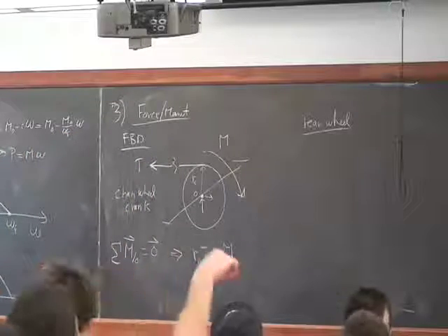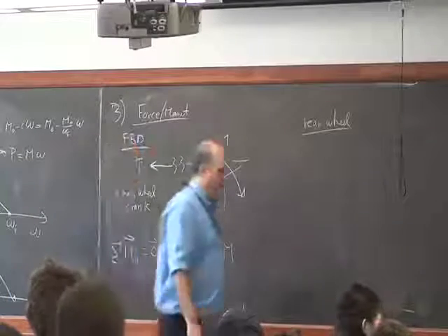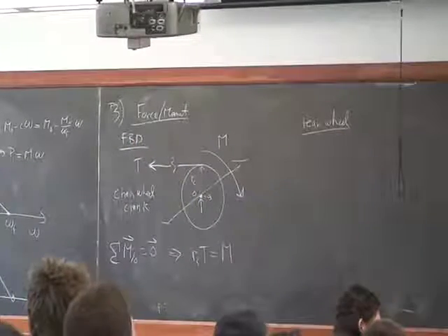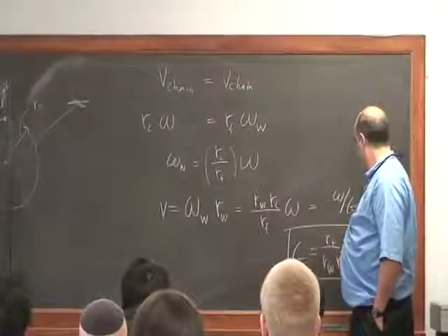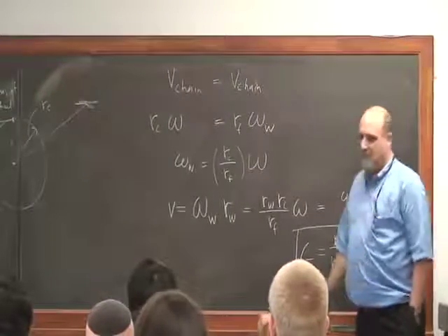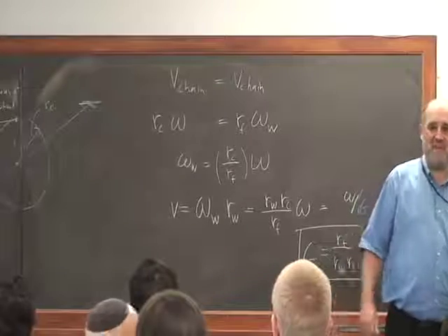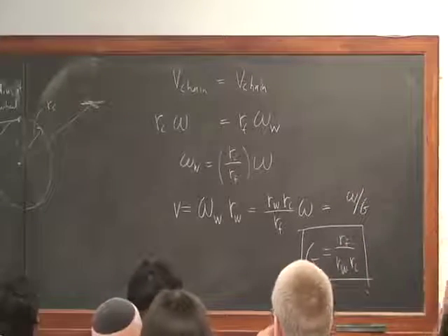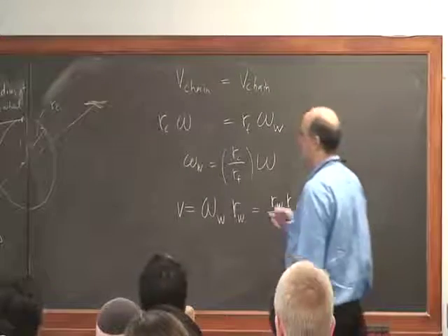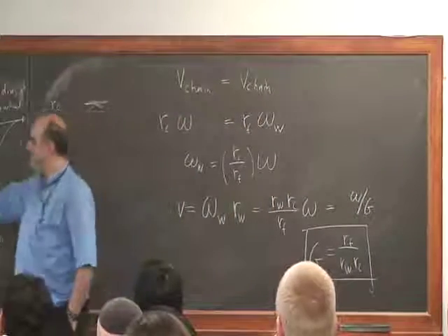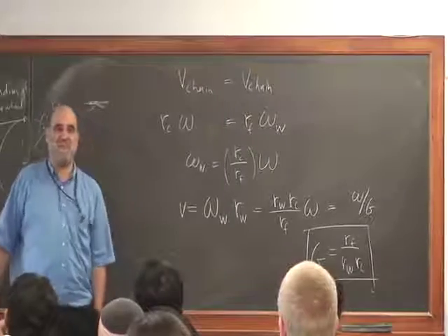Yes? I have a question. Wouldn't that have some form of units, and isn't a gear ratio not supposed to have units? Yes and no. This does have units, and yes, commonly gear ratios do not have units, but in this problem we're taking a gear ratio which is relating an angular velocity to a linear velocity, and so we're stuck with units.